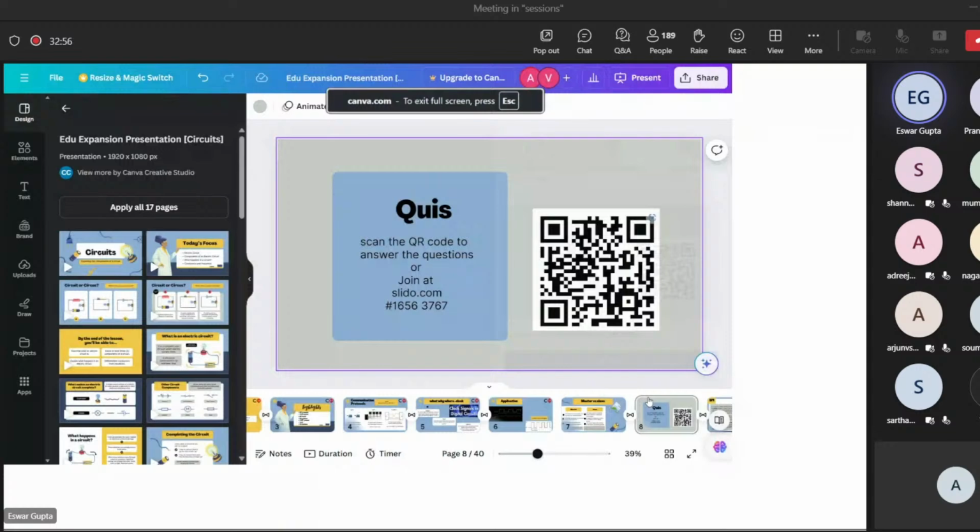And MOSI is master out, slave in. That is, the master will send out the data and the slave will get the data in. Suppose there is an Arduino board and a microphone. Now if the master wants to send a command to the microphone, saying microphone, record the data, what will it do? It will use the MOSI line. Master out: from the master, the data will go out. Slave in: the slave will get the data. So it will send record.